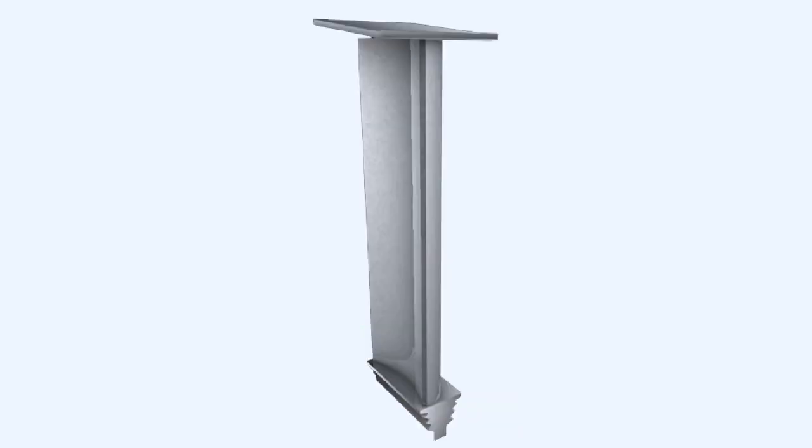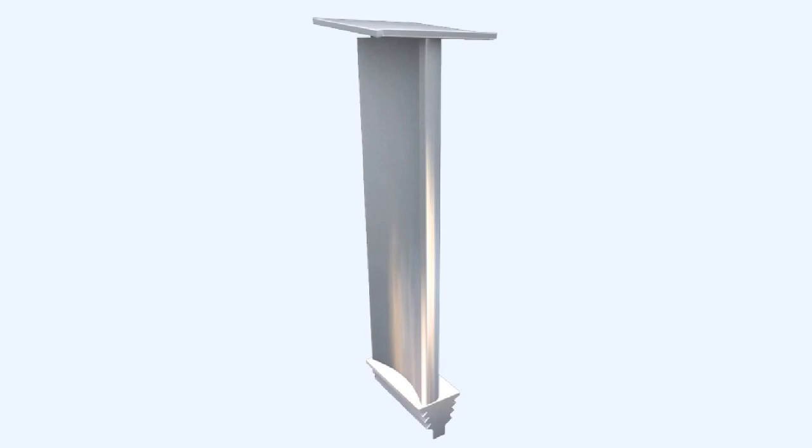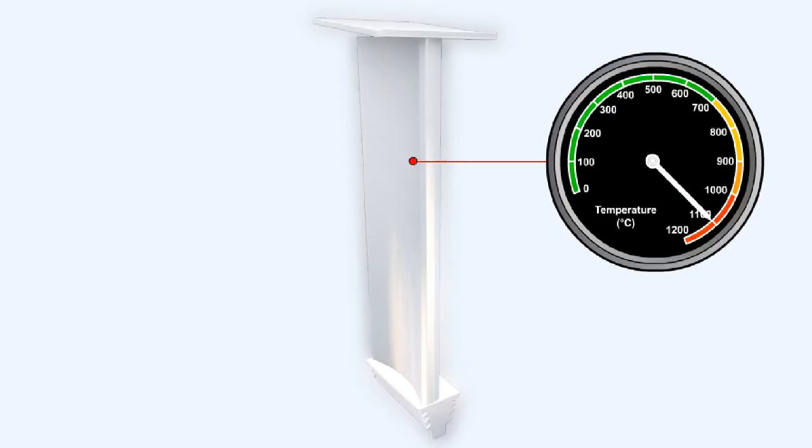The next advance in turbine technology was the use of nickel-based alloys, and these were subsequently superseded by superalloys. Superalloys are a complex mixture of many different metals: chromium, cobalt, nickel, titanium, tungsten, carbon, etc. Blades manufactured from superalloys have a maximum temperature limit of approximately 1100 degrees Celsius, or, if the blades are cooled internally, 1425 degrees Celsius.